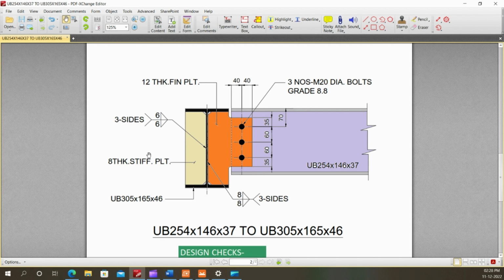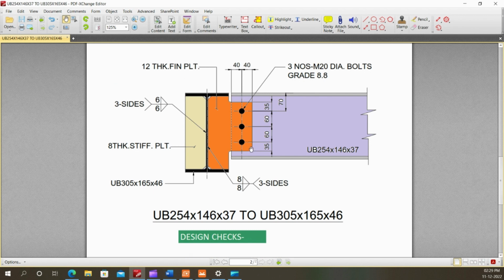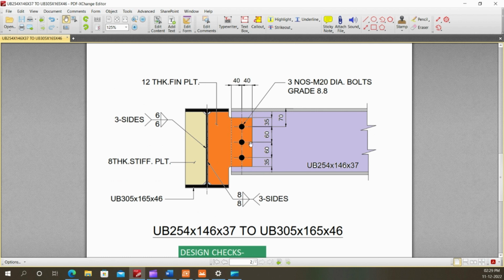The other method, inelastic or IC approach, takes into account the bolt group's ductility, as well as the load distribution that occurs when the bolts begin to yield. This method is more exact, but it requires several iterations and thorough computation. When bolt forces are computed using the above two methods, it has been observed that there is nearly 10 to 12% difference in the findings of the bolt forces. The elastic method is simple but conservative.